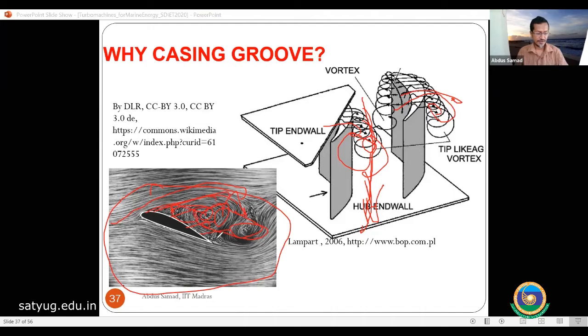For example, you may remember the Indonesian air crash a few months back, I think more than one year back, when they crashed. So what happens when an aircraft is taking off? It is making a certain angle. If the angle is more, there will be more flow separation. If flow separation is not controlled, then it will not get further lift. Rather, it will fall down or behave haphazardly.